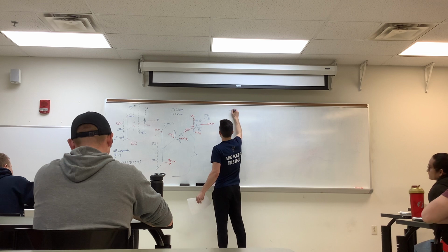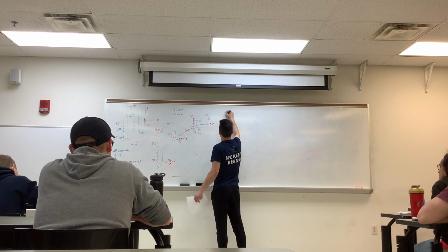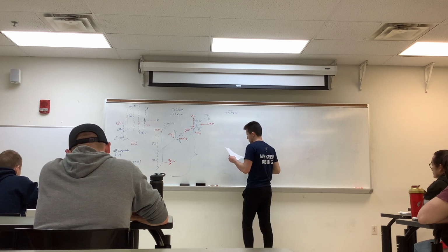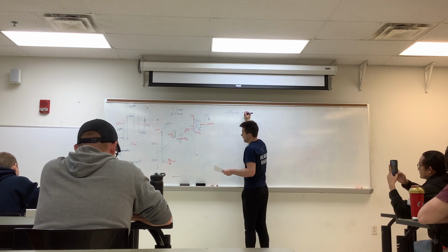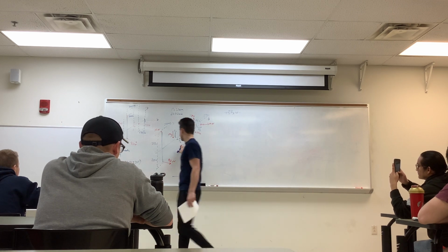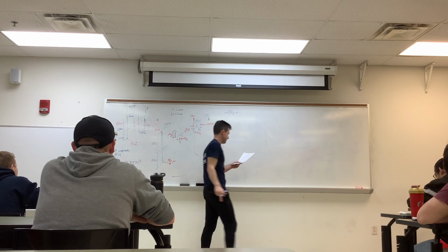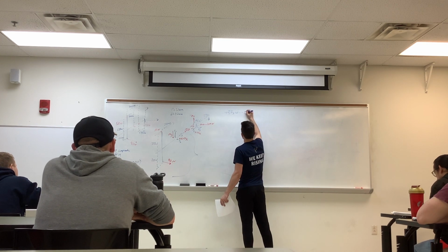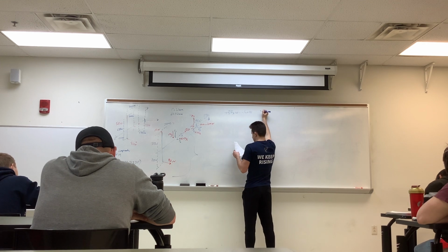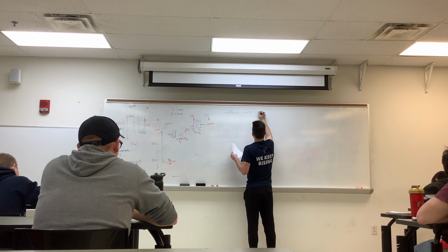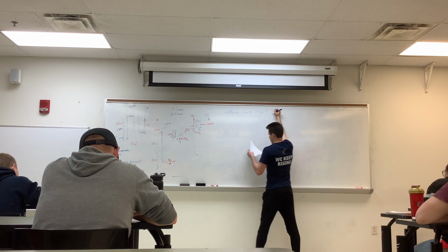the x direction. So sum of Fx is equal to 0. I'm just going to have the right as positive. We have negative Fx and positive 90. So negative Fx plus 90. We get this force in the x direction to be equal to 90 kilonewtons.